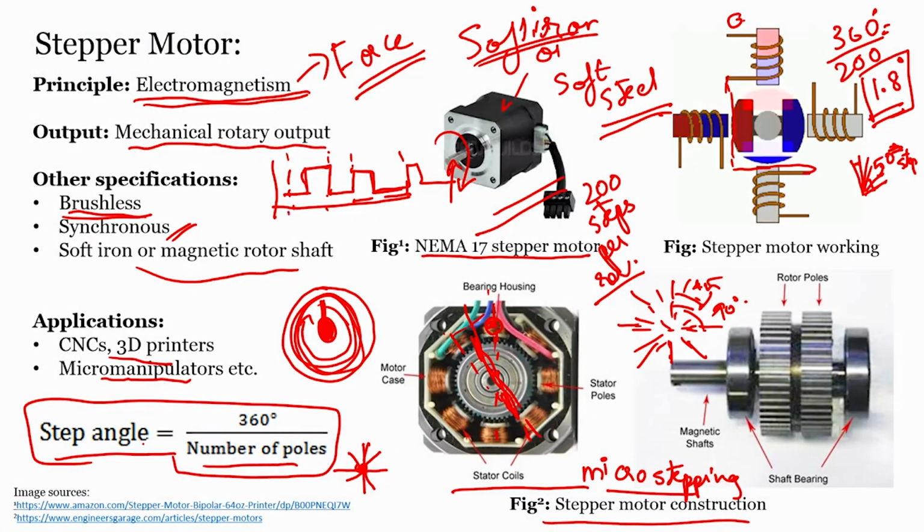I have made it high for 5 millisecond, I have made it low for 5 millisecond. Once that is done, the for loop will come again and will again make the pin high. So, this is how a single pulse is generated.